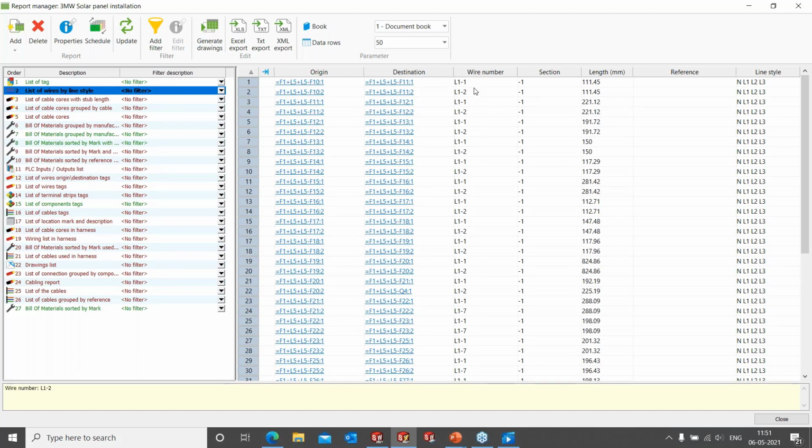So as I told, here there are formula based wires which are being added, which have intelligent properties. So based on that, the designer need not enter any wire number manually. Automatically it will calculate based on the formulas which are associated to it. So based on that, it will just generate the wire number and also the length of it.